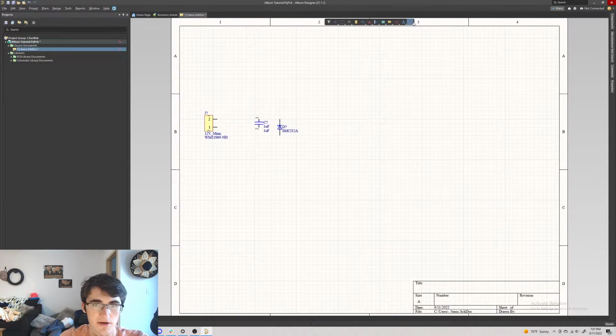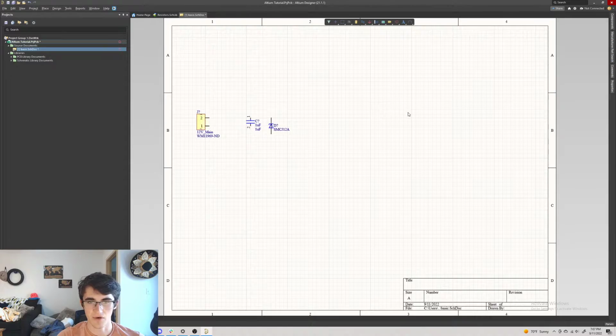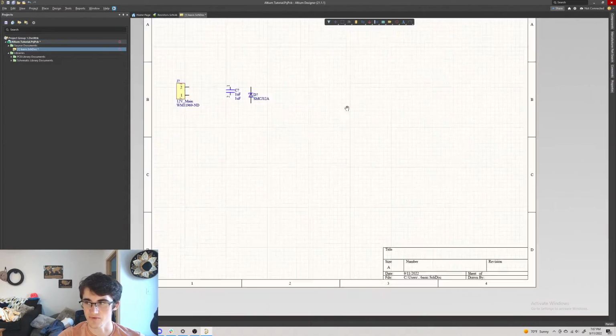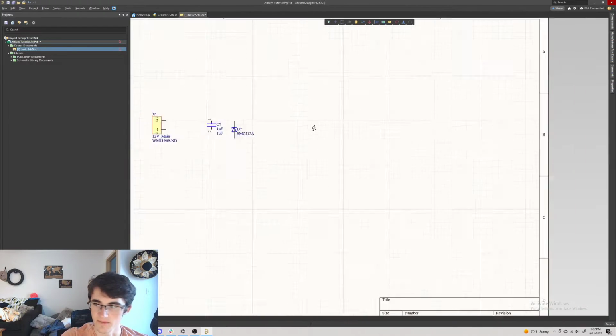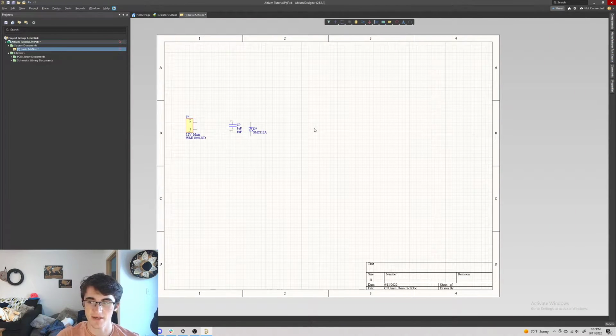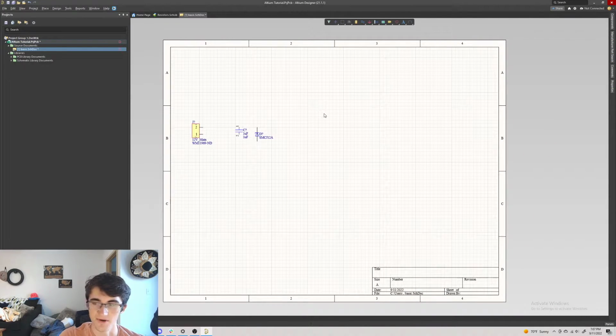Talk about what's up here. We can go through some of these. You can do some of those basic movement tools. I would recommend using Altium with a mouse. Like I said, you can left click and right click, but you can also hold down right click and drag around the schematic, and then press down on the scroll wheel and zoom in or out. If you're using a trackpad with this, it's an absolute nightmare. It's not worth it at all. I would really recommend just going to a lab computer if you're going to do that.